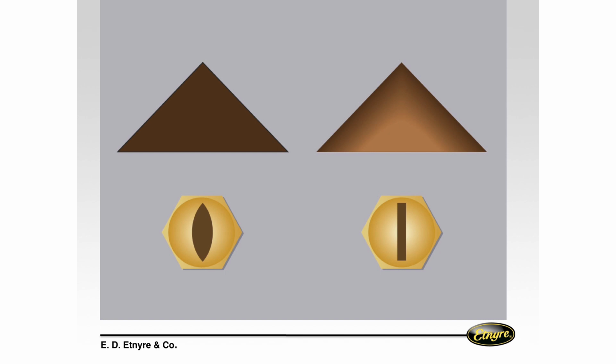Emulsions tend to grab the surface area of those as they're spraying, and they'll tend to give you heavy edges and light in the middle. So you'll see those string lines going down there. So you'll be heavy, light, heavy, light. Everybody uses a multi-slot, multi-V, V-jet, whatever you want to call it, sort of a football-shaped orifice. So as that oil comes out, it dumps more in the middle and gives you a more uniform spray pattern.